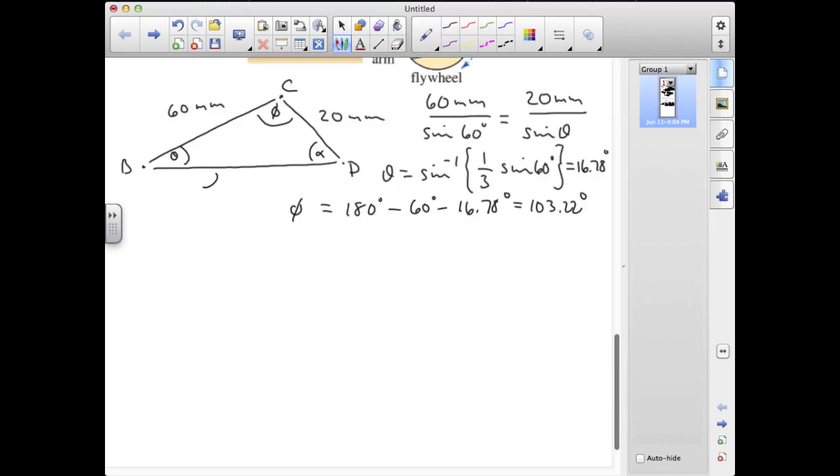I can then find the length of this segment BD corresponding to the unstretched length of the spring. It's not the unstretched length of the spring, but it's still going to give me a reference unstretched length that will allow me to determine the largest compression and tension of the spring under the conditions that alpha equals 0 and 180 degrees.